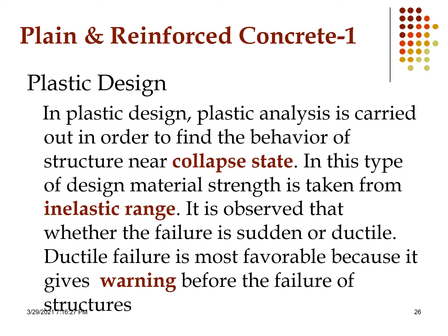Now the other type of design we call plastic design. In case of plastic design, plastic analysis is carried out in order to find the behavior of the structure near the collapse state. In this type of design, material strength is taken from the inelastic range. It is observed whether the failure is sudden or ductile. Ductile failure is most favorable because it gives warning before the complete collapse or failure of the structure.